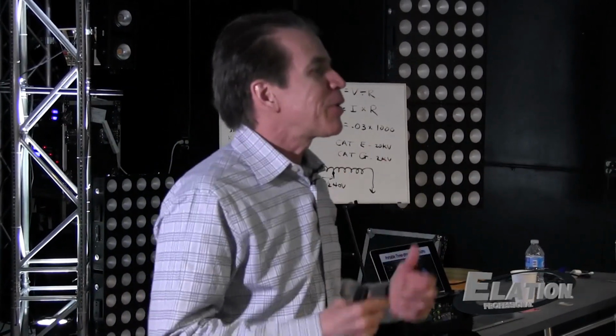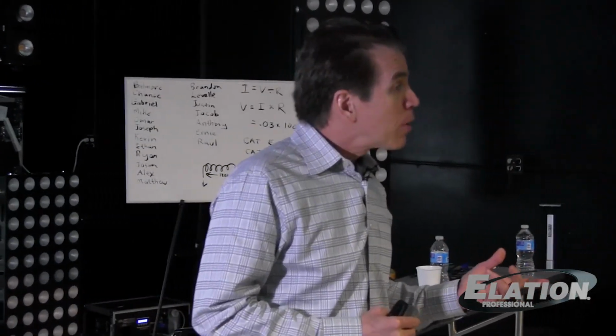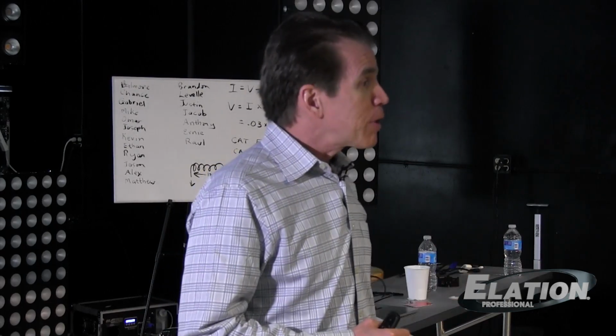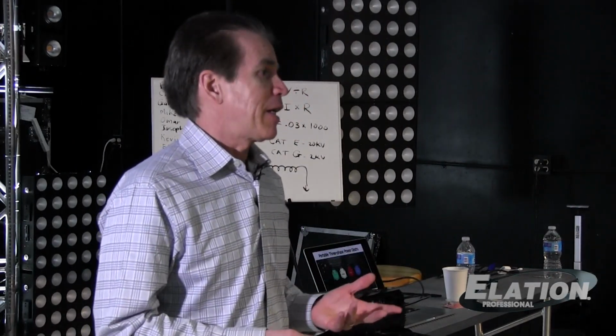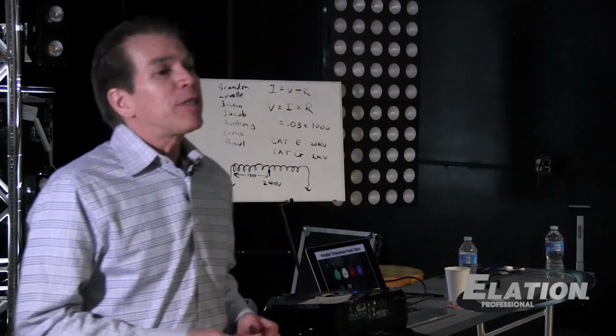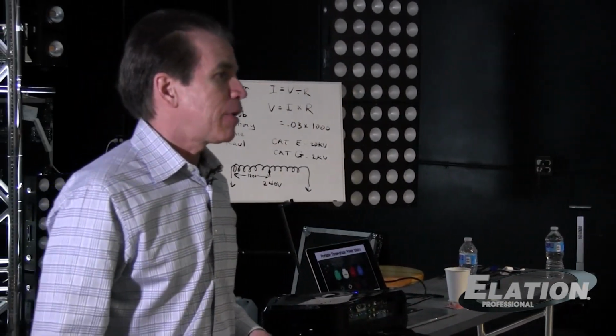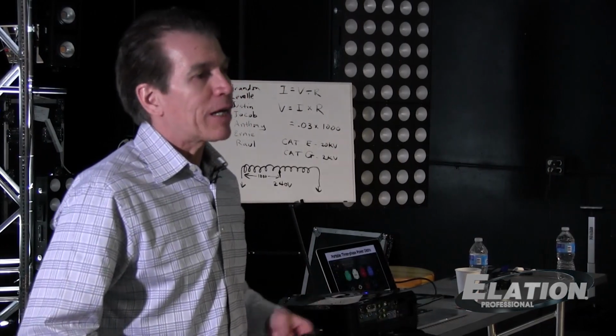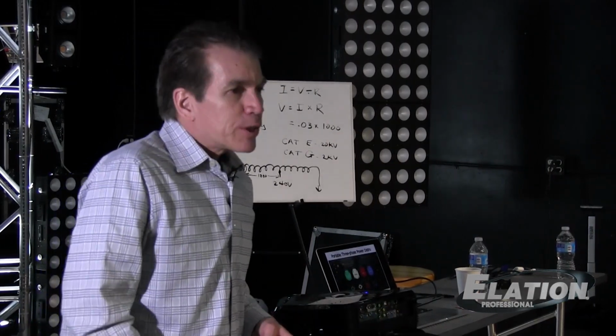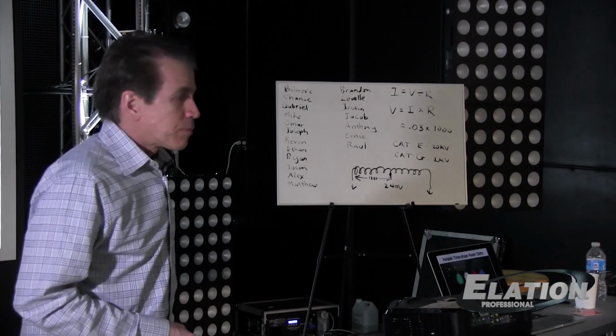Because they're heavy machinery, if you tried to run your washer or your dryer off of 120 volts, it would be more than 20 amps, which means they would have to put in number 10 wire instead of number 12 wire, which costs more money. So instead, they'll give you connections for 240 volts, so now your washer and dryer connections use less than 20 amps a piece, or combined actually. So that's typically what you'll find in your house.